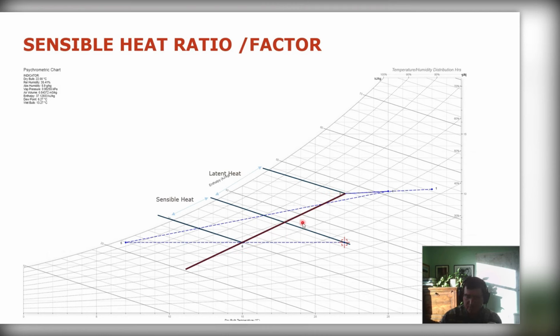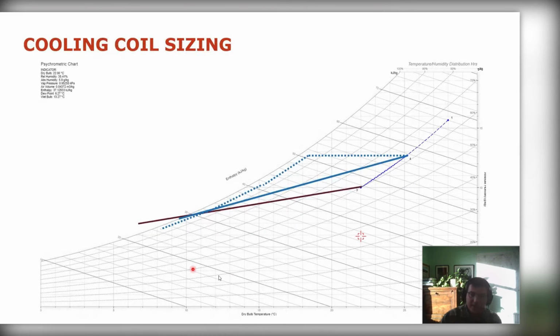So I think that's important as well, if you look at the geometry of your line for the condition of the supply air that you desire, if it's like in this case, then you would want to use a reheat. And if it's coming off, then you can just use an off coil condition directly, as long as you pick it correctly.